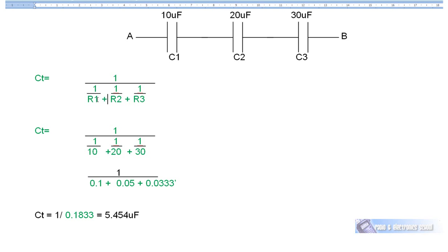I know we haven't done inductors yet, but if you're trying to find the total inductance of 3 different value inductors, you would use that equation, and the technique on the calculator is the same. So inductors in parallel, resistors in parallel, and capacitors in series, if you know this formula, you'll be able to do any of them.